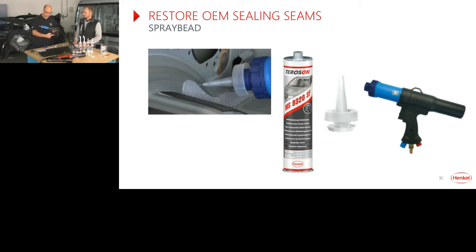And the second air valve, the blue one, regulates the spray air which comes around here, goes in between the two nozzles, and takes the material with it to spray it on the surface. So here we have as well a spray application.